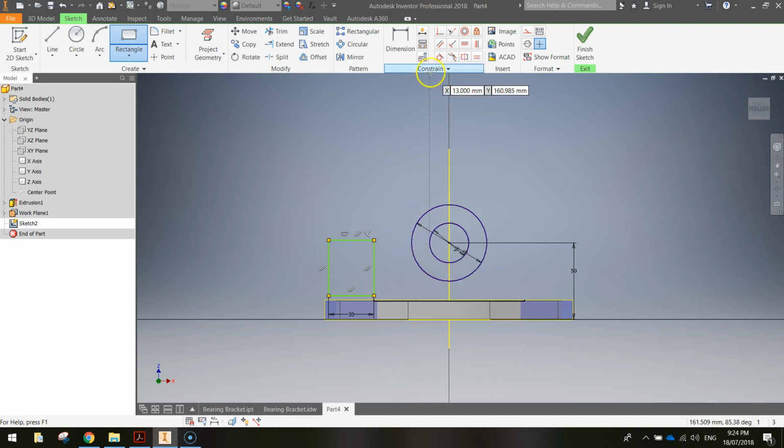Now we're going to use this Coincident Constraint tool again to snap this rectangle to our x-axis. So click the Coincident Constraint tool, click the base of your rectangle, and then come down and click on this base down here. It's basically the origin we want to click on. That's the only thing highlighting there, so click on the origin. And you'll see now that your rectangle is smack bang in line with the origin, or pretty much positioned on the x-axis.